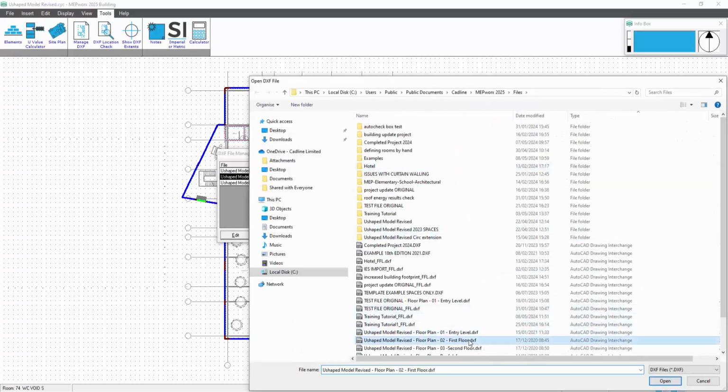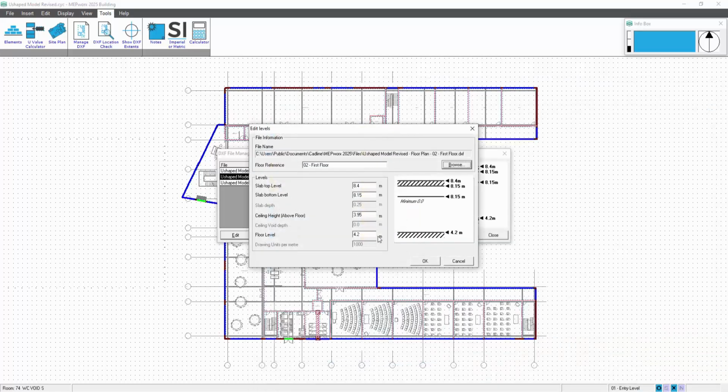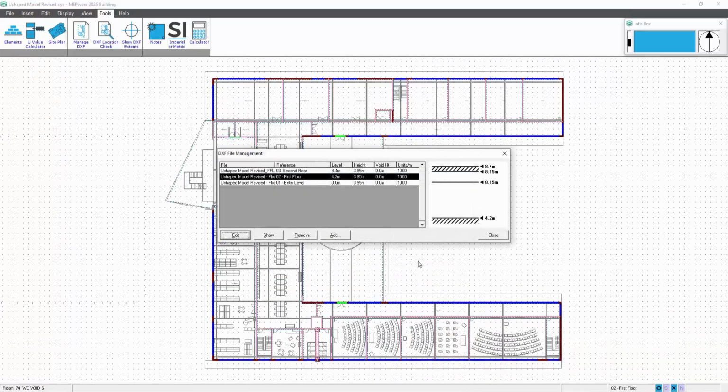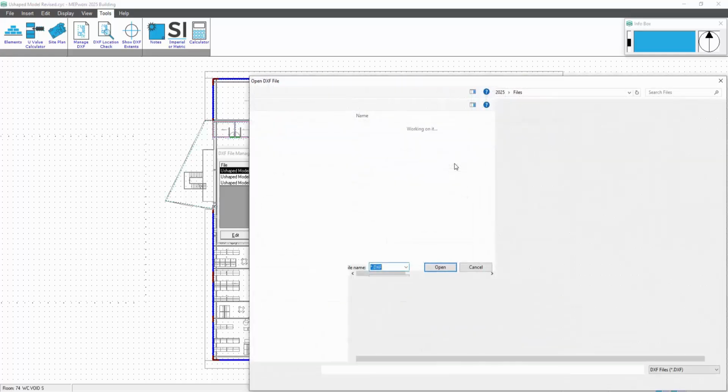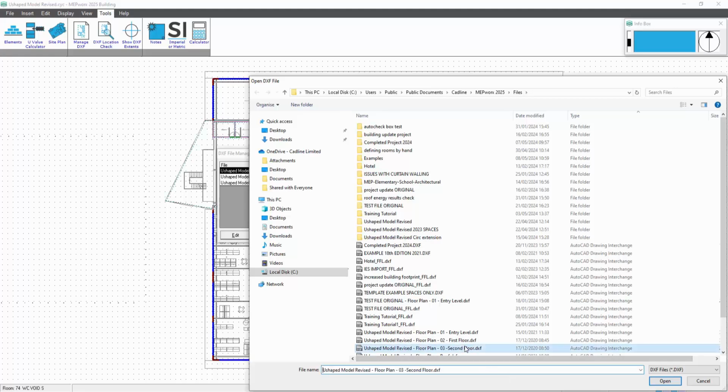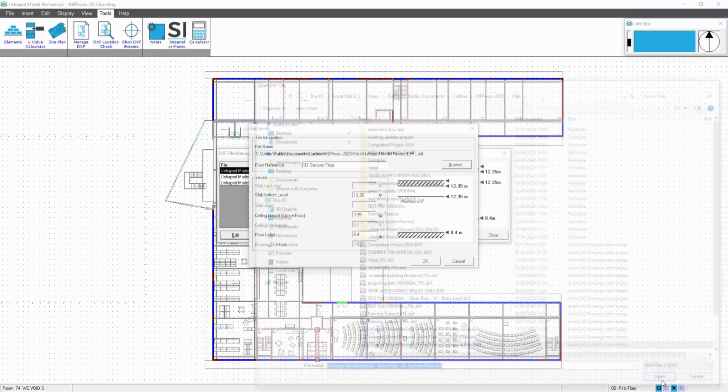The floor plans would be sourced from the CAD system that the original DSM model was generated from. So generally, if it's IES, you would have traced over the model or the DWG file, which we have actually converted to DXF here, and bring that detail in. You wouldn't really want to import the DXF from the dynamic simulation package because they will only generate the DXF based on the geometry.